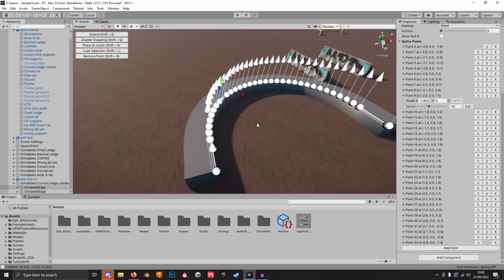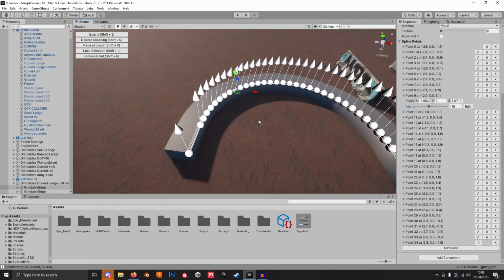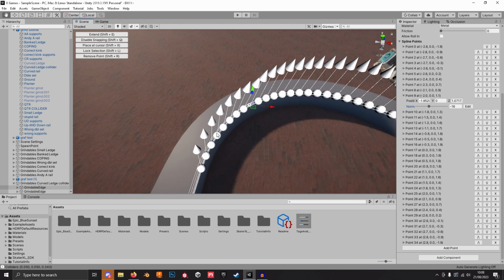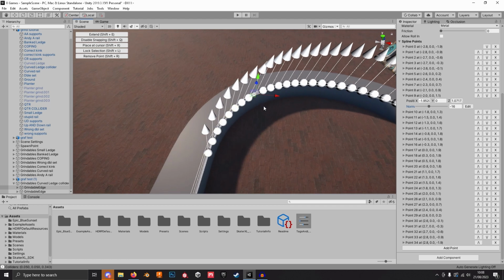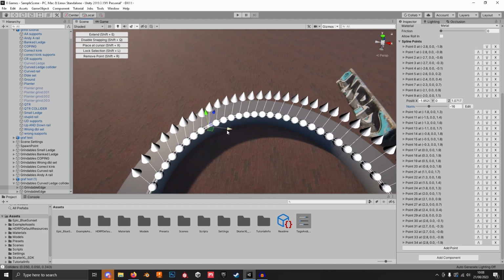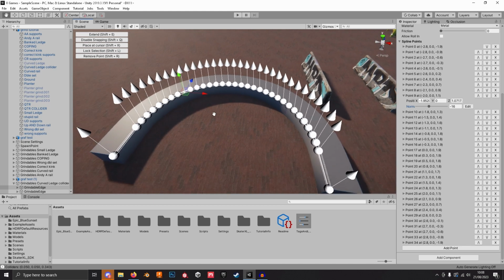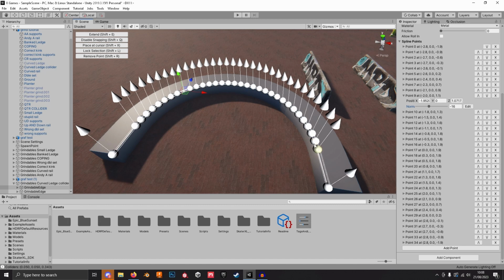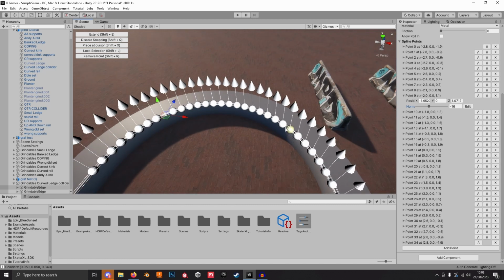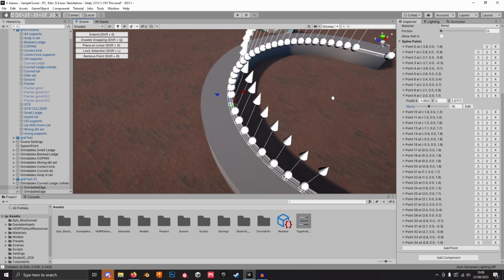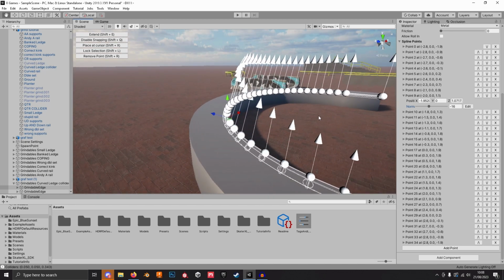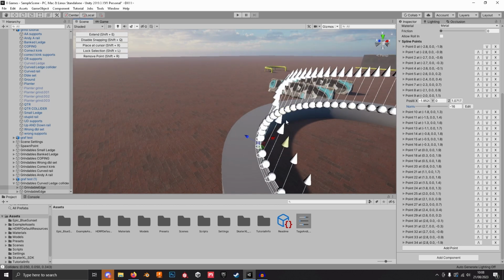Okay, so all those normals have been adjusted. You can see it starts from 0 here, and then it goes 2, 4, 6, 8, 10, until we reach 16, or minus 16 in this case. And then once I get to minus 16, I'll start this side, minus 2, minus 4, minus 6, so on, up until minus 16. Then the rest in here are minus 16, and they just tilt you inwards just slightly, as you can see. Don't have to be too much, but just enough to help tip the skater and keep him on the ledge. If they're up dead straight, there's a good chance you're going to skip across the top as you go around this bend.